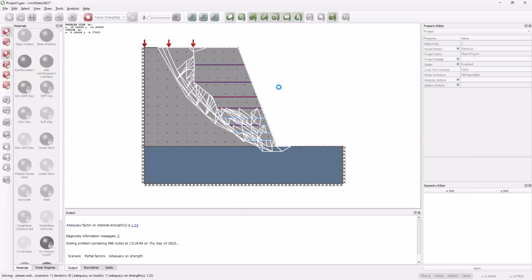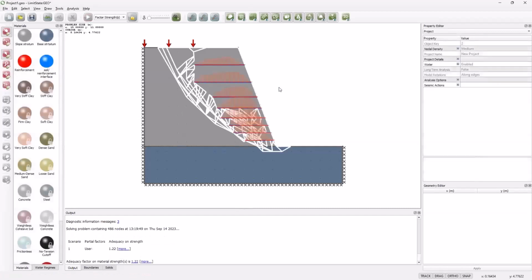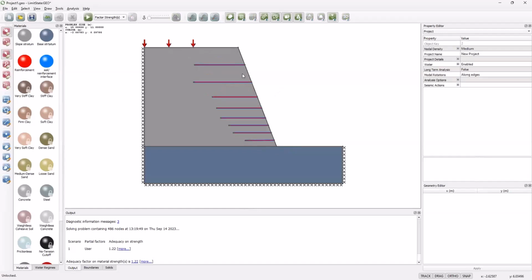What we would recommend in the software is that we model a thin layer of soil on the surface with a slightly higher strength. I've got something changed in the model here. We didn't get that local failure. But anyway, we generally recommend putting a thin layer of soil on the surface with a higher C' value that is sufficient to suppress that local failure. And that's quite good at representing those scenarios I described a bit earlier, where you've got some local strengthening of the face.